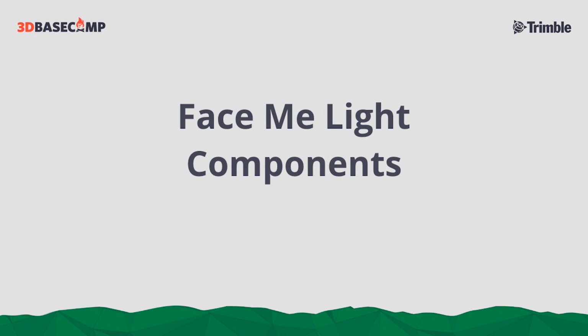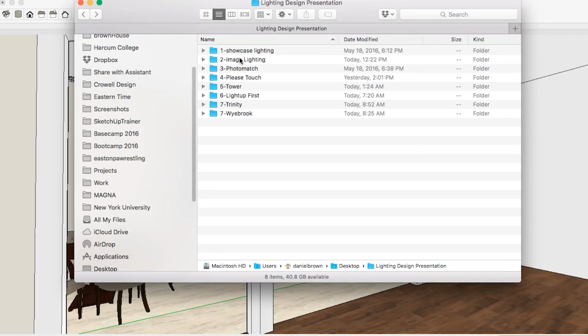So another way that you can use and leverage SketchUp is with FaceMe Components. If you're not familiar with FaceMe Components, they allow you to take a 2D image and have it always face the camera. More importantly, with FaceMe Components, you can have any of those light chandeliers, anything that's very hard and complicated to create, as an image and place it within the model. So again, I'll quickly demo here, just showcasing that.